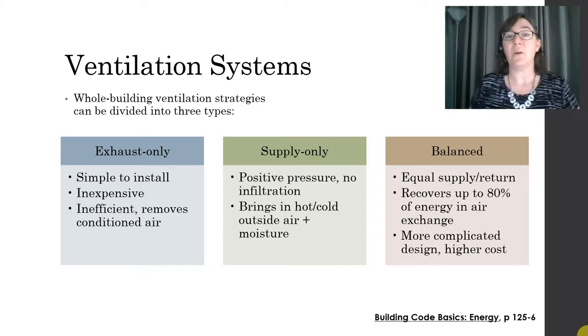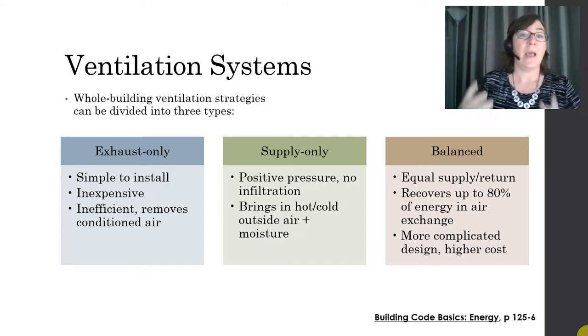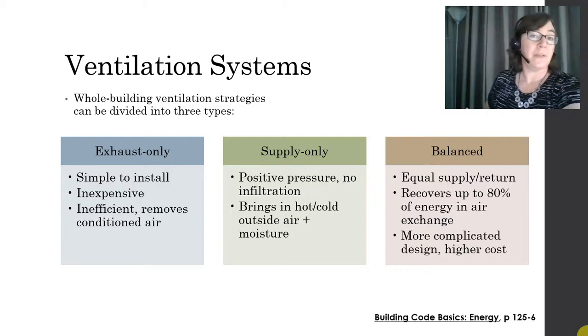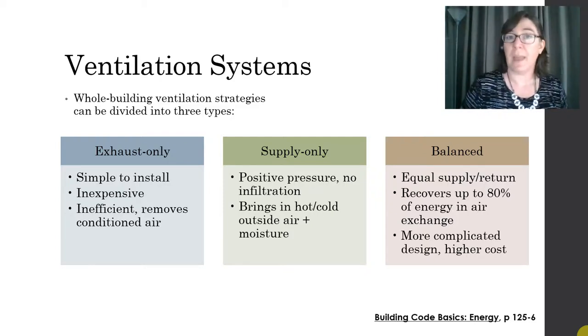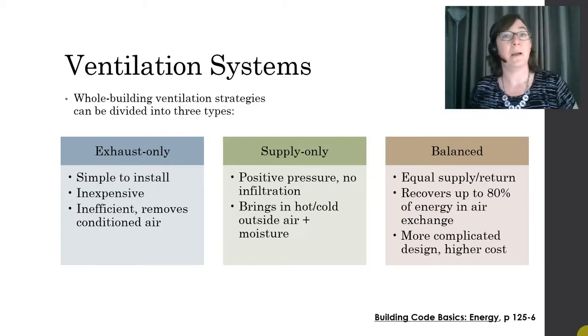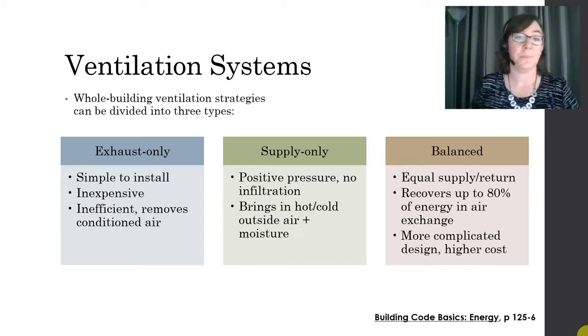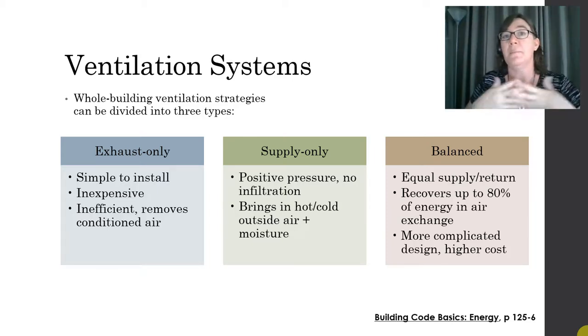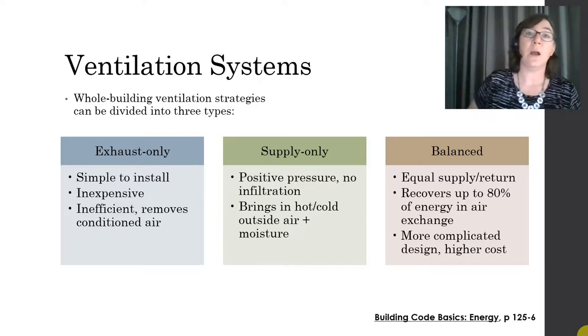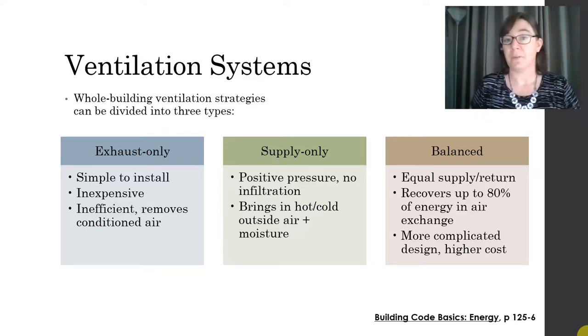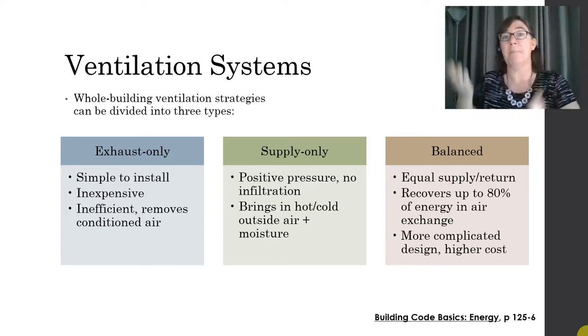A supply only system has the positive side that there is positive pressure and no infiltration, so pollutants from outside don't get in. But the downside is that you are constantly bringing in air from outside and you bring in the heat and the moisture that comes with it. So we've come to the balanced system, which balances an equal supply and return.